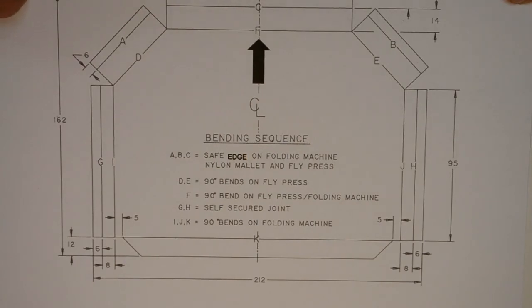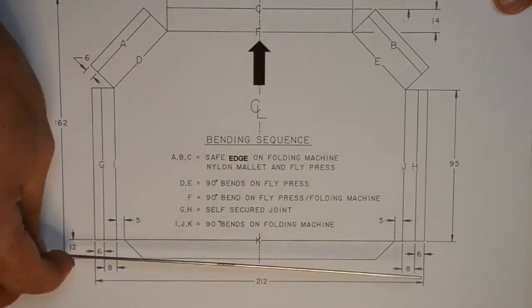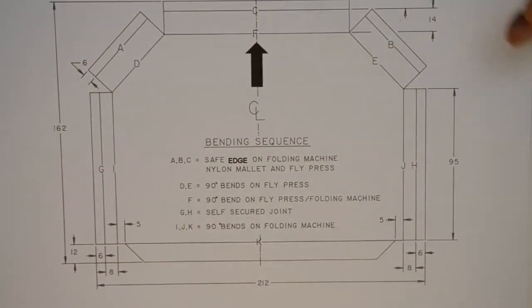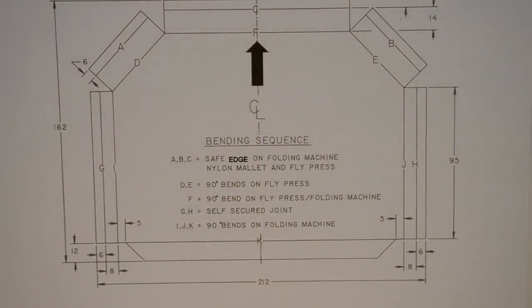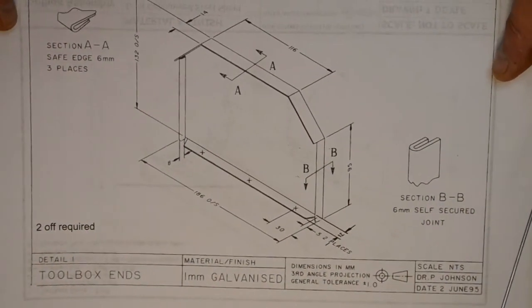Once we've established this, we can then establish that one, and once we've got the top and bottom lines put in, we can start to do the rest of the dividing up that is required to produce our finished product. And it all revolves around the centre line. In most drawings the centre line would be a little bit clearer, but that symbol there is a critical one to look out for, because that's telling us exactly what we need to know. With the datum on here, there's the datum, slap bang in the middle. That's where I need to establish first, and then I can start to develop my finished product until at the end I come out with something which looks a little like this.